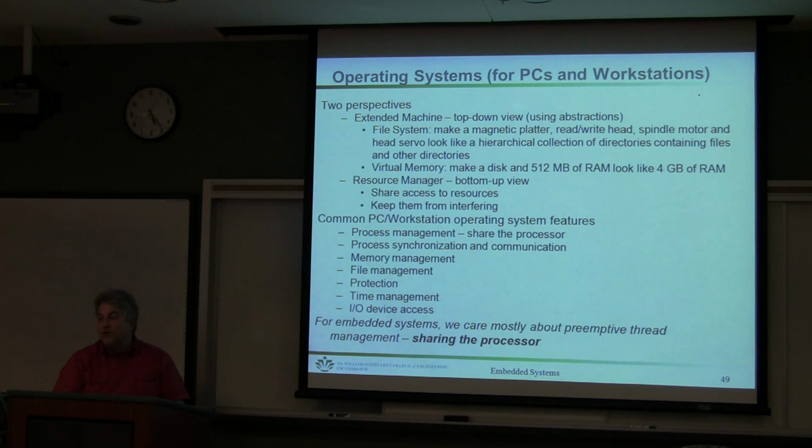Now for an embedded system, mostly what you're worrying about is how do I share the processor? Very infrequently does an embedded system have a file system. I'll give you a good example. If I am running my stove, and I've shown the embedded board that came with my stove, that will not have a file system because I'm not reading to and writing from that device.